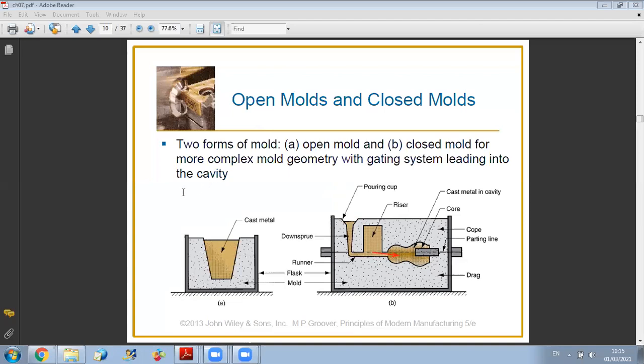You should have that the total solidification time of the riser should be higher than the total solidification time of the main cavity, okay? Because it should be able to continue to supply molten metal until the solidification process in the main cavity is over. In addition, this is not the only condition.